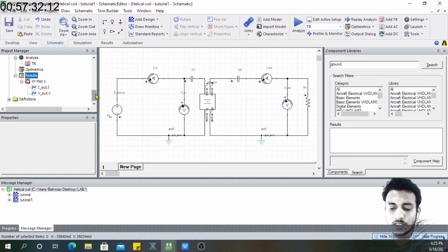Now you can try with different kinds of coils. You can try a little more complex circuitry. Maybe you can use an AC to DC converter, that is a rectifier on the output side, and then test on a DC load or something like that, right? Battery load, you can use a battery load. You can do a lot of stuff, but it will take time. This was the simple test circuit, but it will take time if you consider a practical circuit application. You can create an inverter on one side and a converter on the other side. So this can go on and on according to your need and application, but the gist is the same and the way to do it is the same.